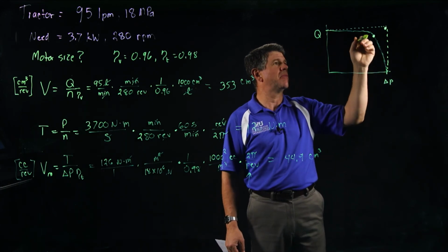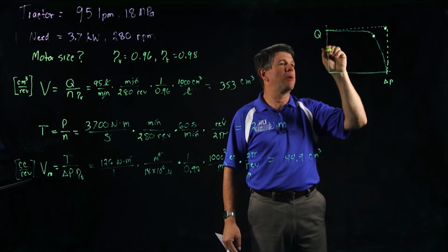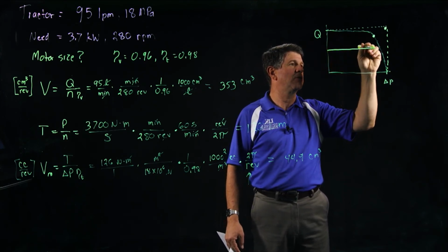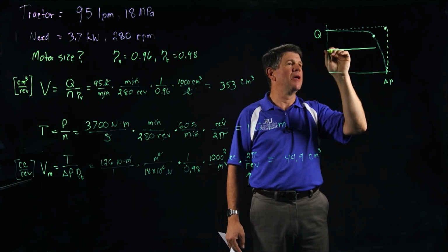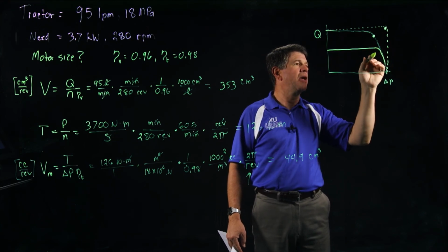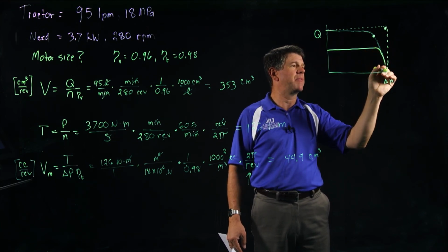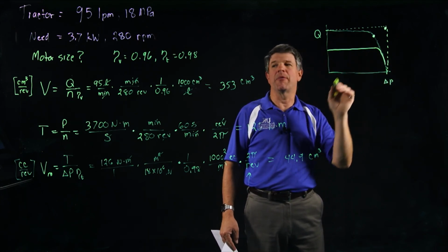And again, I can operate inside the curve. Unlike an engine where I'm kind of stuck on the outside of the curve there, I can operate down here just by saying I'm going to limit flow rate. So I'm going to say, okay, I'm going to put a flow control valve in there or something, and I'm going to limit the flow to this speed, okay? And so that'll allow me to operate anywhere on that curve until I come up and hit this outside curve where it starts to roll off. So that gives me a lot of operating envelope in there.